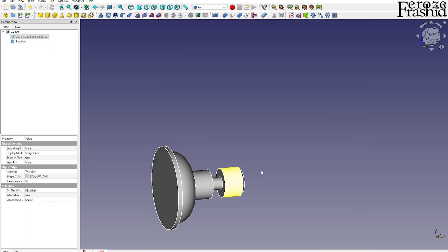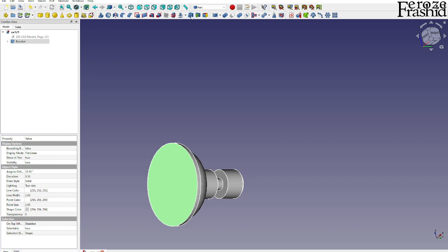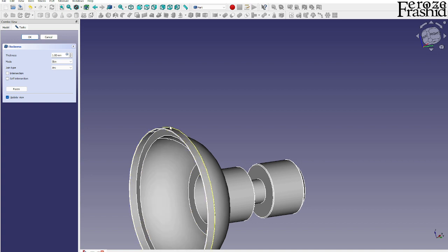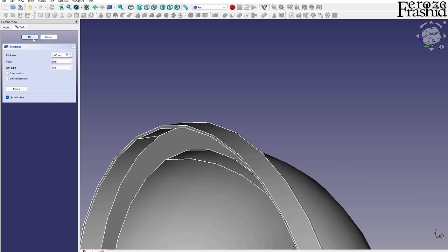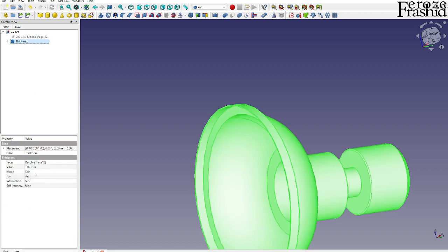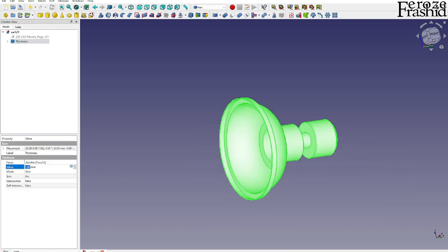Now if you had a cross section and it showed a 5 millimeter thickness all around, the easiest way to do that is apply the thickness tool from here. So select this face and come here and select thickness, and right now it is 1 millimeter, but it's going outside. I'm gonna go ahead and say okay with that, and then come back to it and update it if we needed to bring it inside. So now it's going outside. Say I want to make it 5, so it's going outside. What if I wanted to have the thickness applied to inside? So I'm gonna say -1.